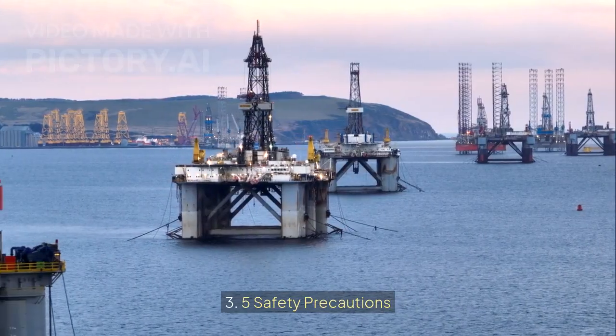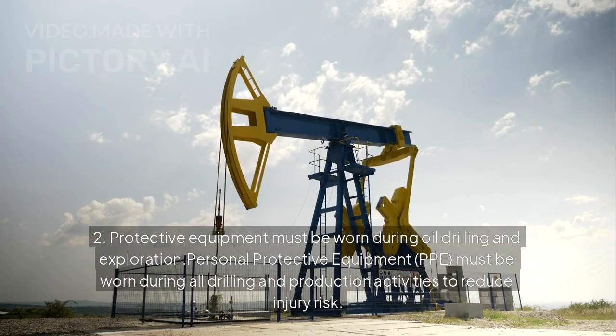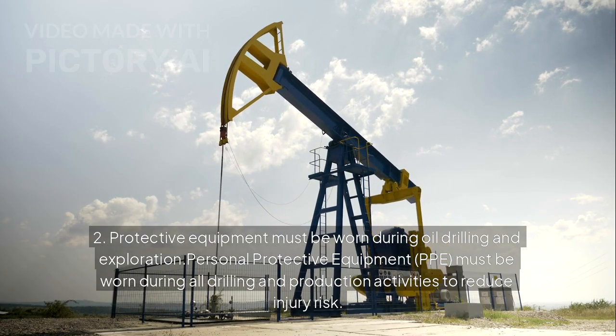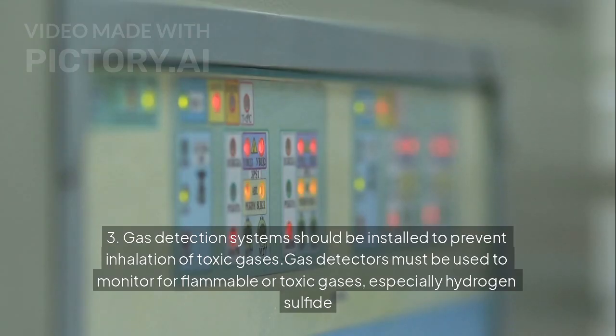3. 5 safety precautions. 1. Protective equipment must be worn during oil drilling and exploration. Personal protective equipment, PPE, must be worn during all drilling and production activities to reduce injury risk. 2. Gas detection systems should be installed to prevent inhalation of toxic gases. Gas detectors must be used to monitor for flammable or toxic gases, especially hydrogen sulfide.